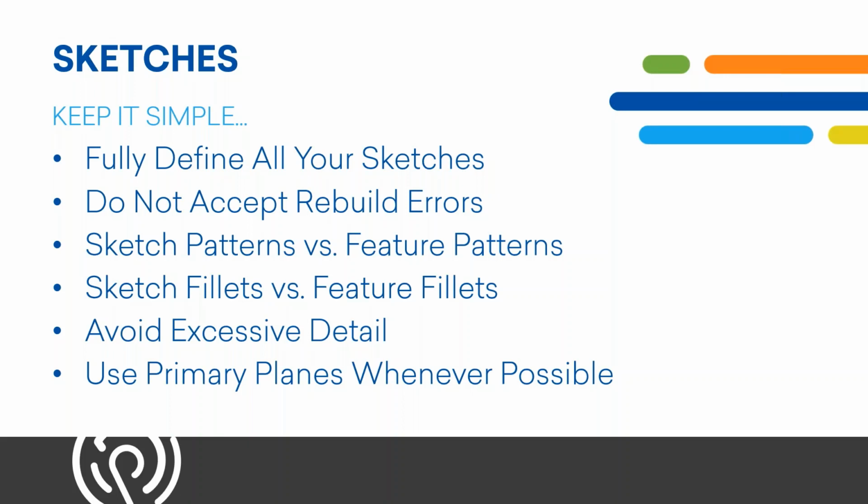When you're working with a large assembly, do you need to know every filleted edge, or do you need to know all the text or different things like that? If not, with working with an assembly, maybe you're just doing interference detection, or maybe just assembly or whether or not things work well together. We're going to recommend that you put patterns into your models using features, and then your fillets, we're going to recommend that they are features as well, and we'll talk about that placement as well.